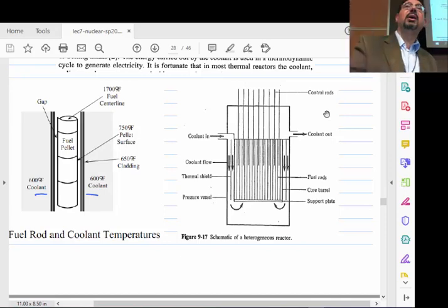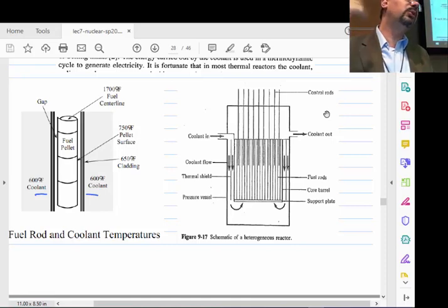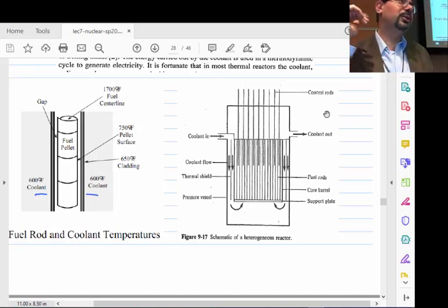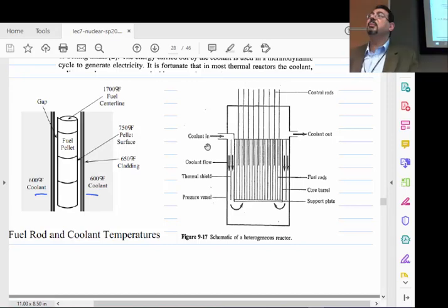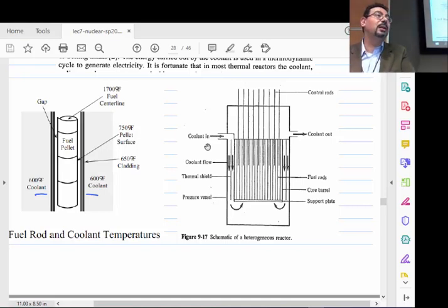And of course all that water went through the reactor and back into the sea. At that point there was concern that fish would eat that polluted water and you would end up with radioactive fish in the Walmart near your house, eventually. But the point is, nuclear safety is all about that coolant. If we have redundancy of cooling circuits, a pumping system, a pumping system on battery, a pumping system on solar panel, and a pumping system on wind turbine, and if you have an abundance of cooling circuits ready to cool, you will not have a problem with decay heat.